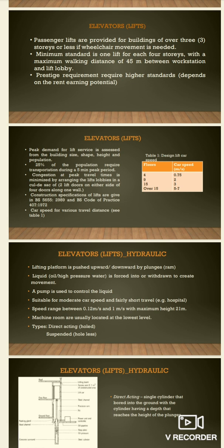Prestige requirement require higher standards depending on the rent earnings potential. And elevator lifts, peak demands for lift service is assessed from the building size, shape, height, and population. 25% of the population require transportation during 5 minutes peak period. Congestions at peak travel time is minimized by arranging the lift lobbies and cul-de-sac of 2 lift doors on either side of 4 doors along one wall.